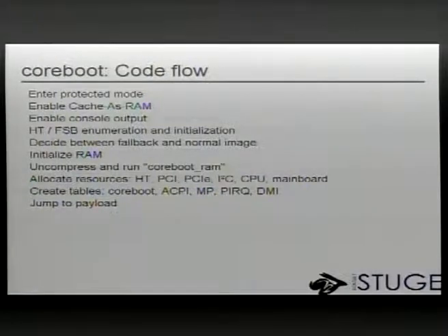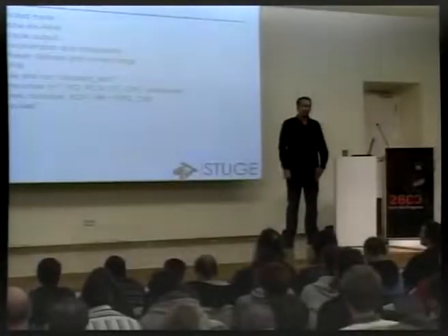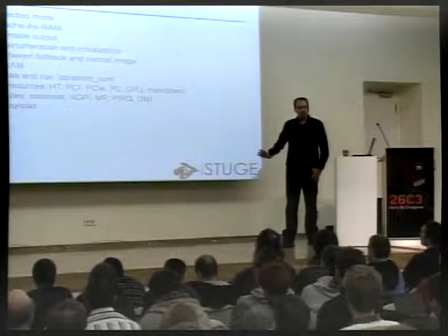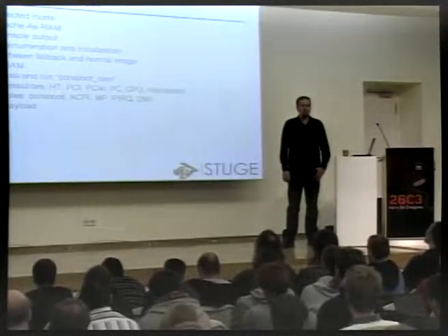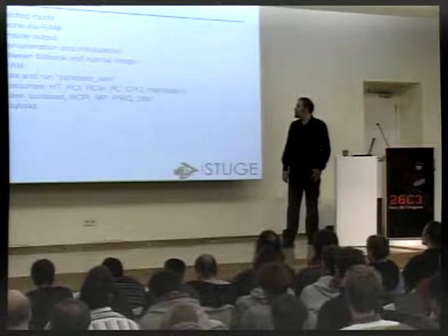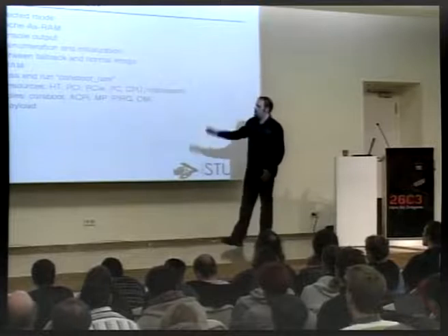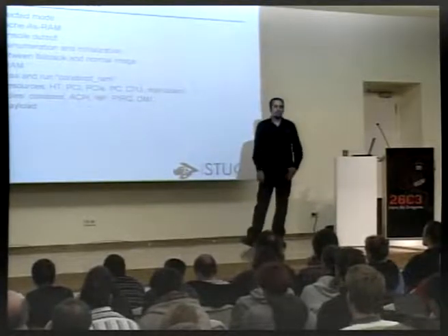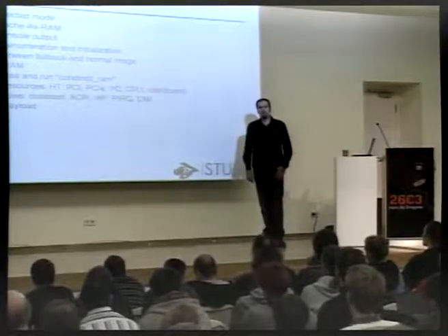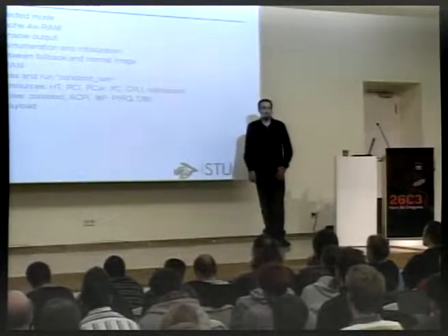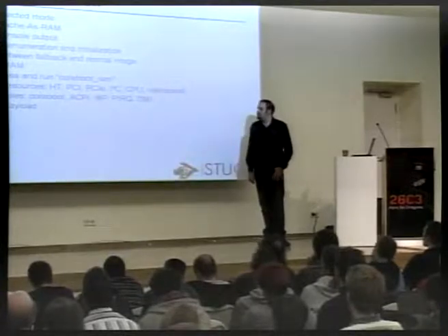So the PCI and the PCI Express and all the rest of the stuff that needs to be configured, I/O ports and interrupts and DMA. That code is generic, and you don't really have to change it per board. So that's nice. But sometimes the mainboard requires some specific configuration as well. Maybe there's this odd function on this mainboard, only on this mainboard, and you have to do some manual setup or resource allocation for that.